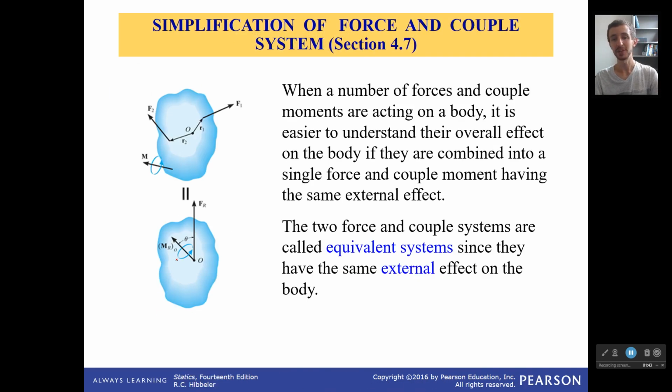So, how do we do this? Well, what we're going to be doing is we're going to take these forces, we're going to take these moments, and we're going to combine them into a force and couple system that is equivalent. And when I say it's equivalent, it means it has the same external effect on the body as the set of forces and moments that we have replaced.